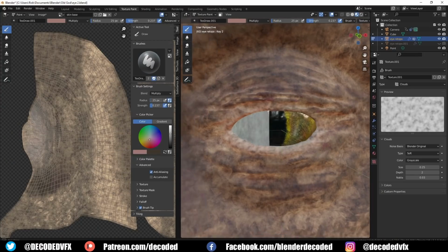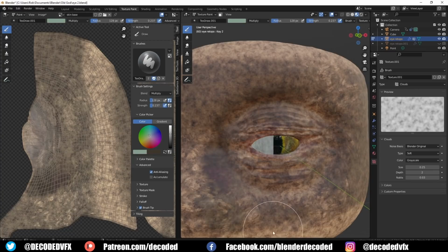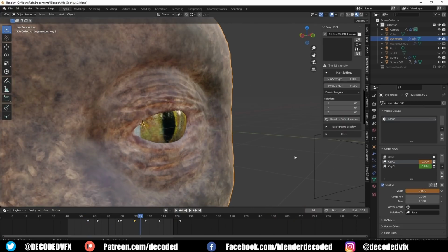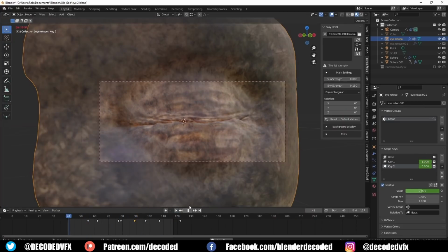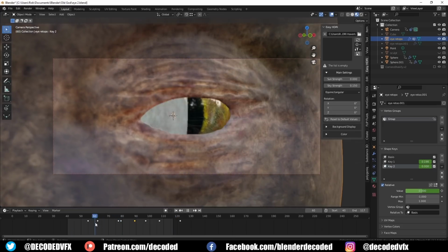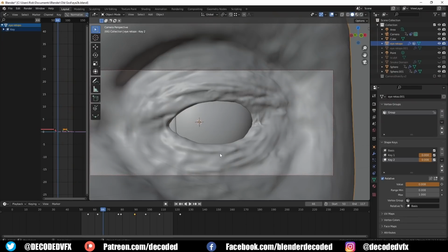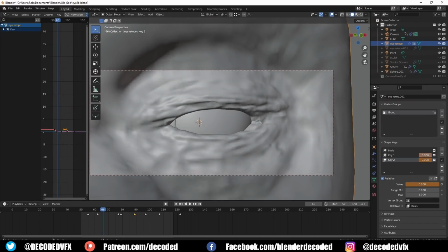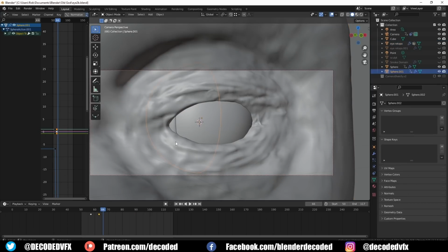I made this really simply just by cutting a sphere in half and rotating it around the eyeball as the eyelids open. To operate the actual eye itself, I used shape keys, or blend shapes as they're known in other 3D programs. That allows you to basically store different positions into a mesh, and then you can just merge between those positions by animating it with keyframes. So I made one shape key that just opens and closes the eye, and I made a few shape keys to add a little bit of movement to the eyelids so they kind of bulge as the eye moves around.